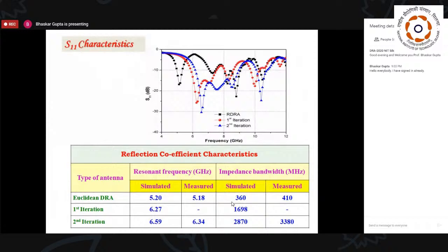correspondingly multi-band operation. You see, that's what we succeeded in tuning the antenna performance by changing the indentation factor by once again changing the indentation width, keeping the indentation length same. As a result, this is something which you observe.